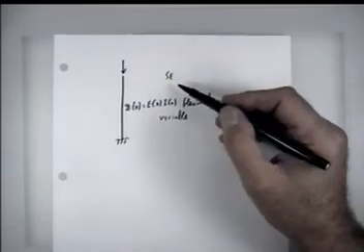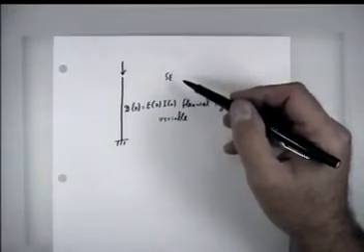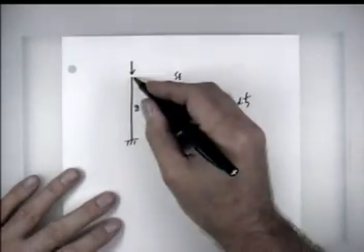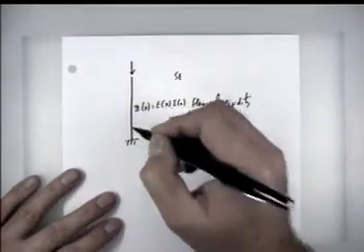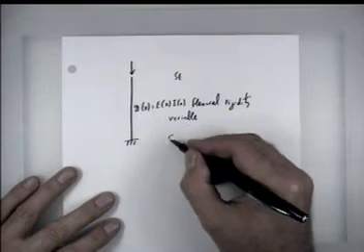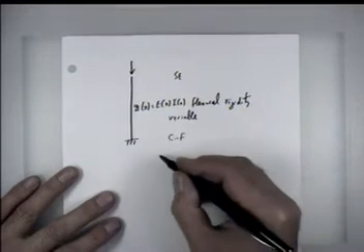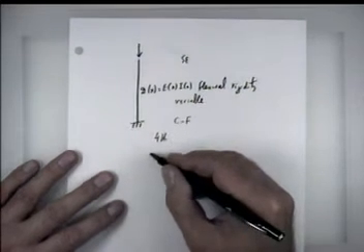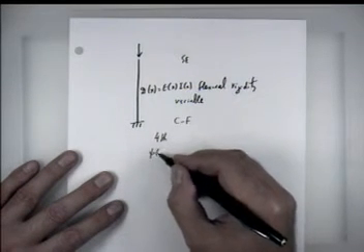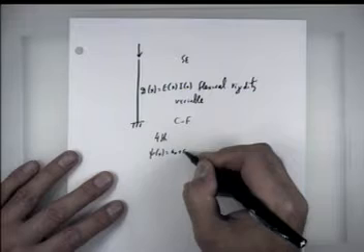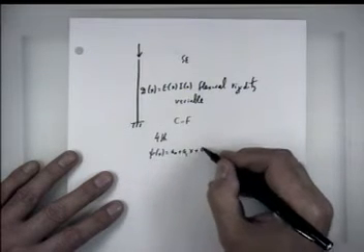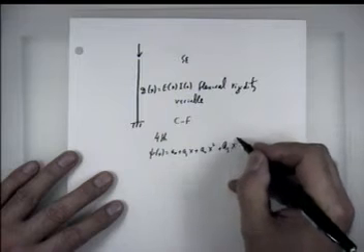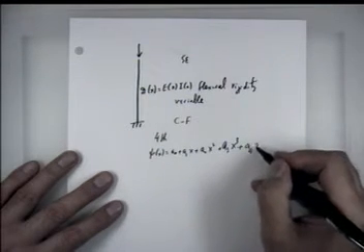Now, what did I write here? What you have to do, if you remember in one of the homeworks, is to find, first of all, clamped-free beams as a fourth order polynomial. That is a mode shape, say psi of x equals a0 plus a1x plus a2x squared plus a3x cubed plus a4x to the fourth.